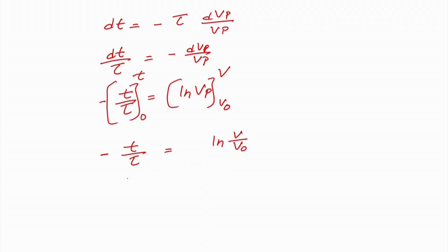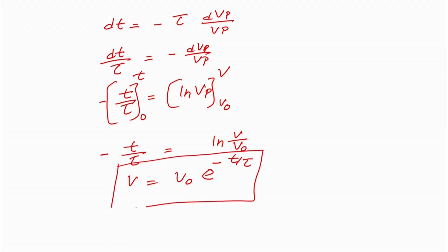Now, you can write it as v equal to v naught into e raised to the power minus t upon tau. So, you can find out that for the Stokes regime, if a particle has been thrown in a stationary fluid, how the velocity of the particle will change with the time. Okay. That will be a function of relaxation time and the initial velocity v naught.